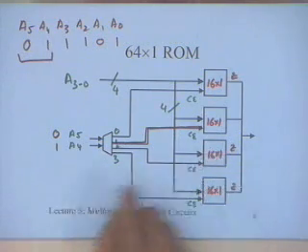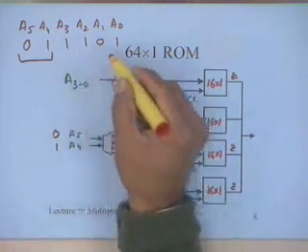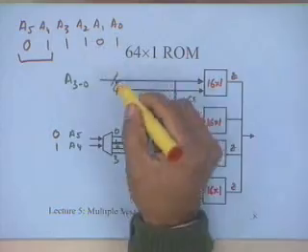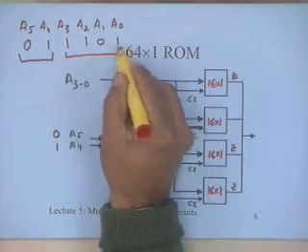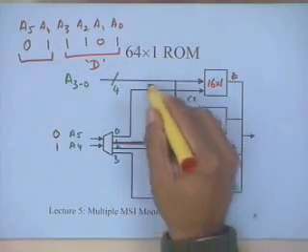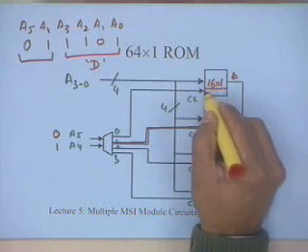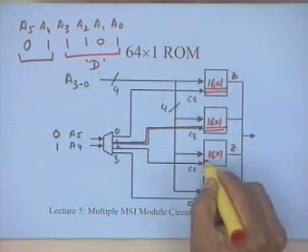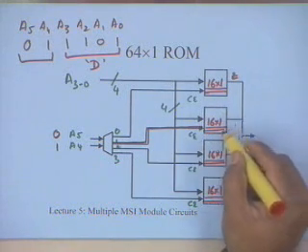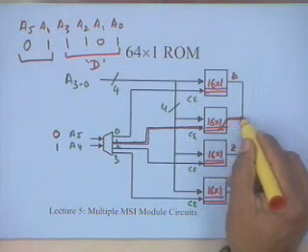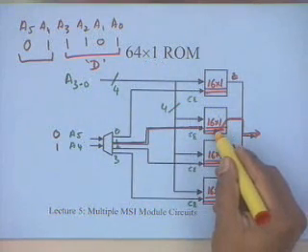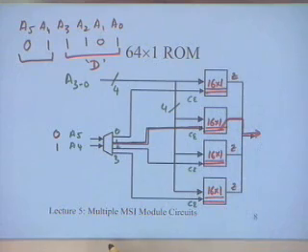And because this is active, and depending upon the address lines, this address corresponds to 1101, which is D in hex. Of course D is being accessed in all of them, but the other outputs are not important because their output is Z. So whatever is stored in this location is going to come out over here. Of course it's only 1 bit, so whether 0 or 1, whatever is stored here is going to be available here.